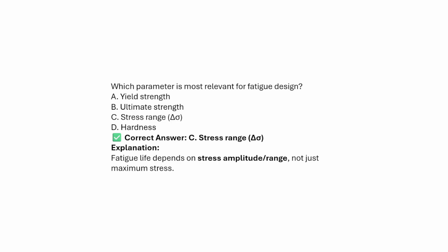Which parameter is most relevant for the fatigue design? Yield strength, ultimate strength, stress range, hardness. The answer will be stress range. The fatigue life depends on the stress amplitude and range, not just the maximum stress.